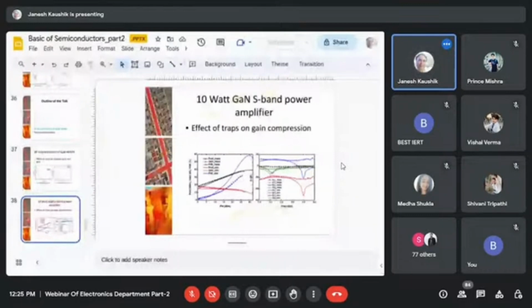PAE means, in gallium arsenide technologies the PAE is around 40% maximum, but here we can go around 70%. The 30% reduction in power wastage gives us the advantage to use this technology for different applications, like EV electric vehicles. This device will be the workhorse because in the lower frequency domain, in the kilohertz, we can achieve in the pulse mode more than 90% power added efficiency, and that will save huge electricity, not only in charging but also in discharging.